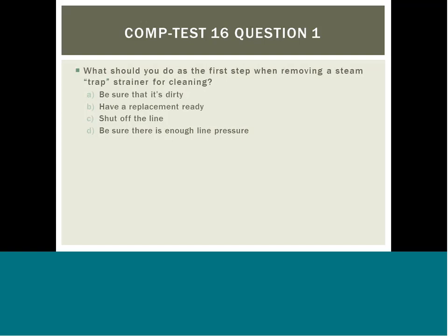Comp Test 16, question number 1. What should you do as the first step when removing a steam trap strainer for cleaning? A, be sure that it's dirty. B, have a replacement ready. C, shut off the line. D, be sure there is enough line pressure.